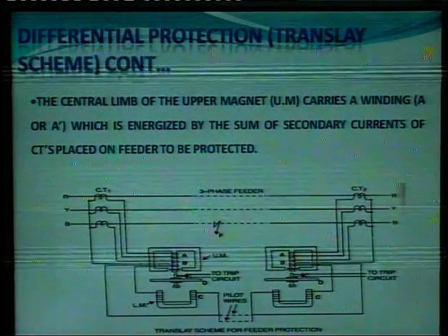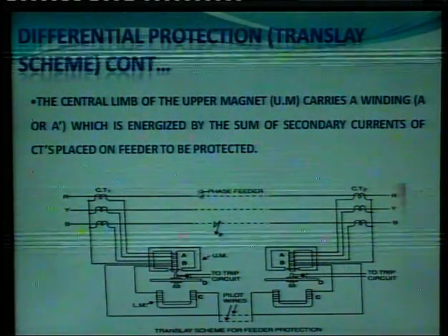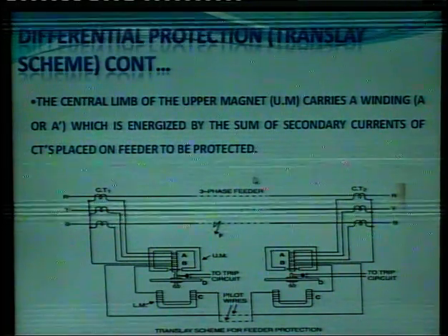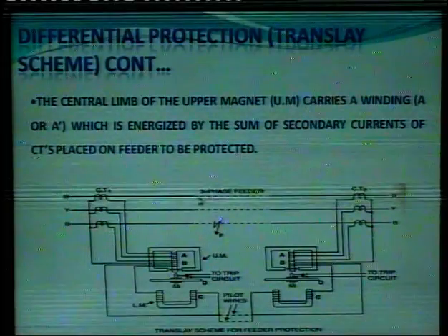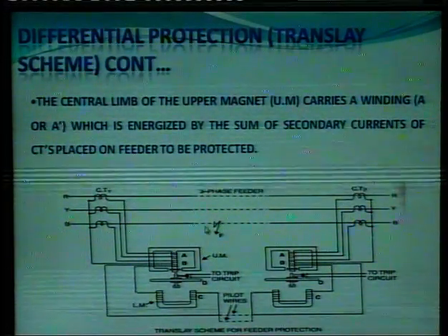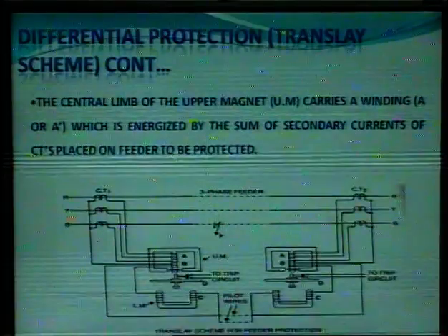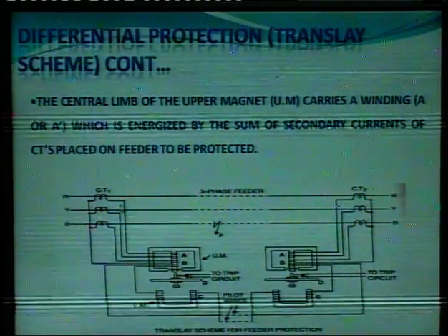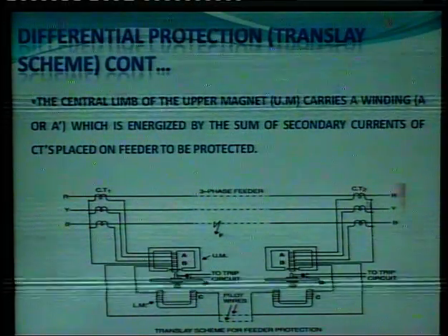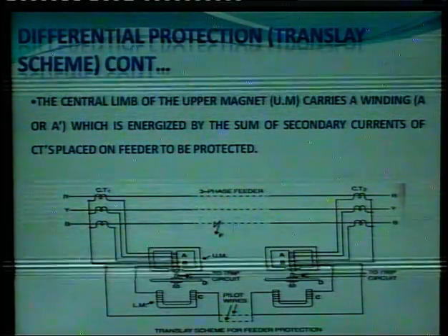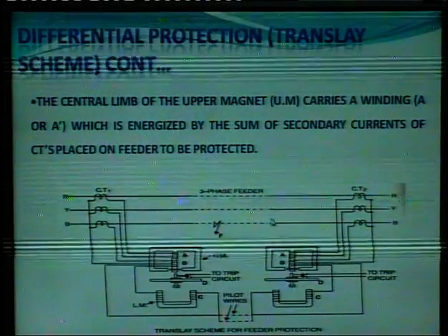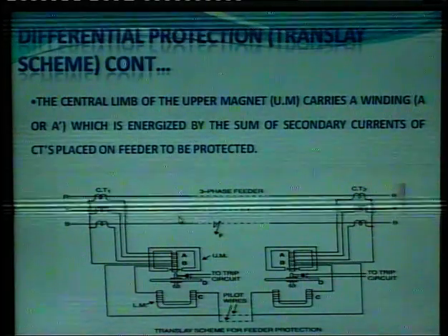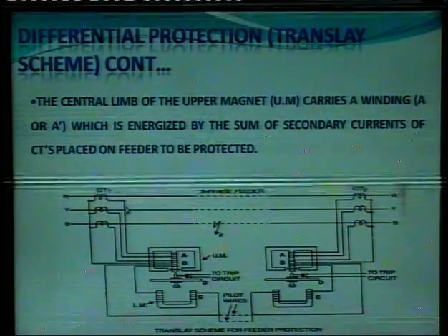So, see, this is a diagram. Now, as you know, for the differential scheme, the component which we want to protect is kept in the center, and on both sides of this component we have to connect the CTs. So, this scheme is known as the differential scheme. So, here we are doing the protection of a feeder. We have a feeder, and on both sides of the feeder we have a set of CTs.